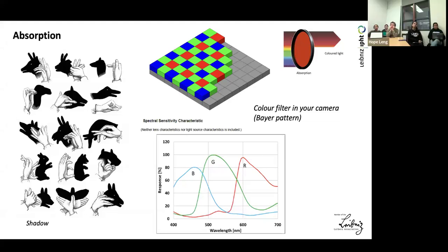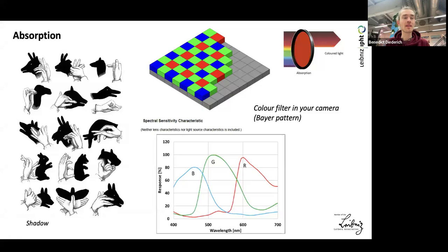So then you can ask yourself, wait a second, if I want to actually use something that has these color absorption things, but at a very small scale, because these things match the pixel size. So the pixel size could be 1 micron, 2 micron. So this is very, very small. And that's why we don't perceive something like that. You really see the resolution of color cameras technically is much lower than monochromatic. But now because these are small enough that it starts to really match.